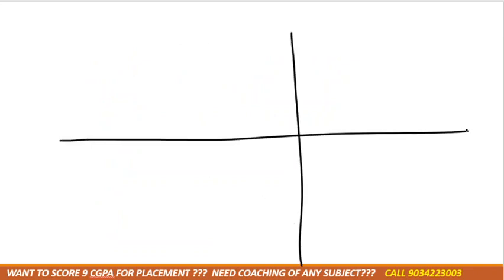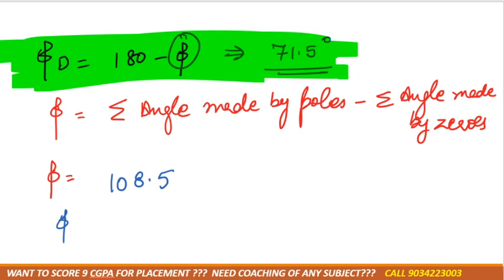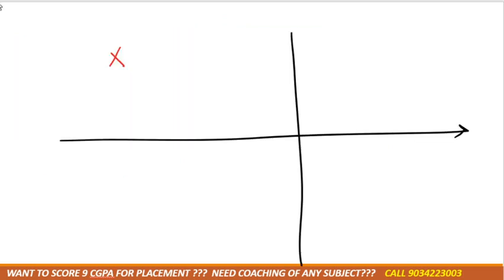Okay, so its final graph we will make like this. As we calculated the angle of departure, it was how much? We got it as 108.5, right? There were poles like this, zeros here and a pole here. As you can see, draw an angle, it's 0, 90, 180, something like that, right? So draw an angle of departure of 108 degree.